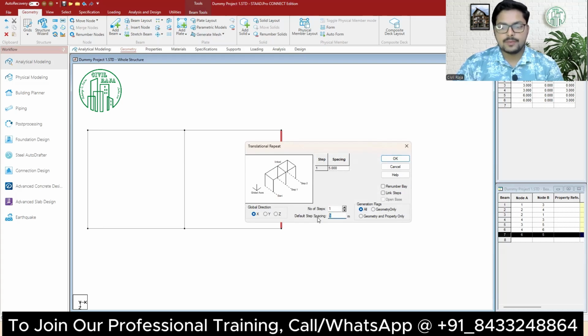Let's see. I'm just making 3 over here. Click over here, and the spacing will automatically change to 3. I have not checked link steps, and I'm keeping it as all. That is not an issue because I have not inserted any property. So either you go for geometry only or you go for all, there will not be any kind of variation in your structure.